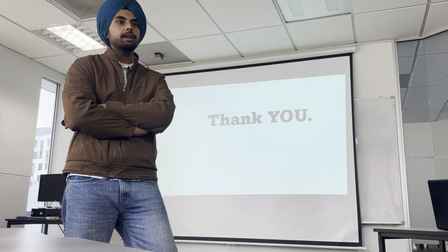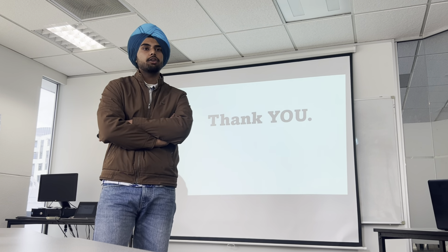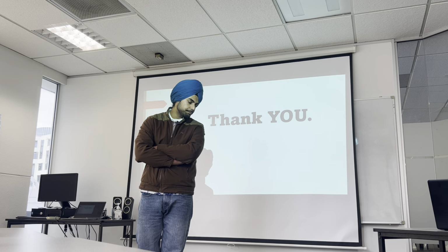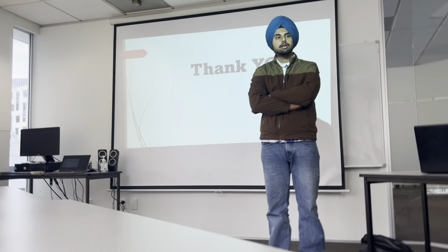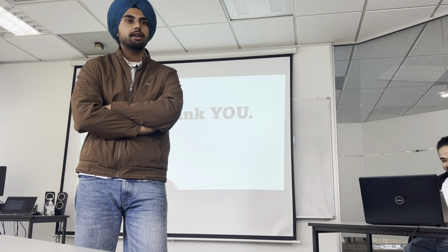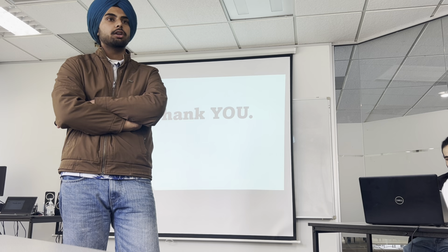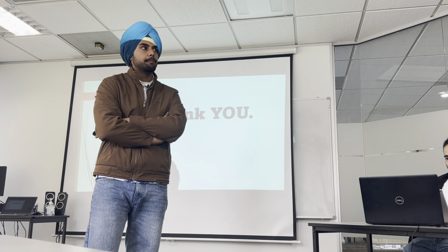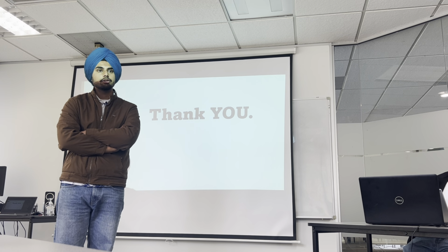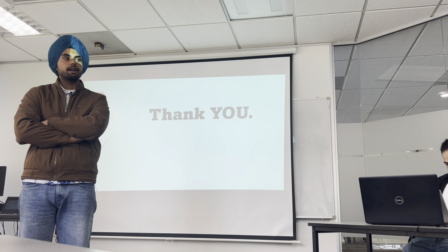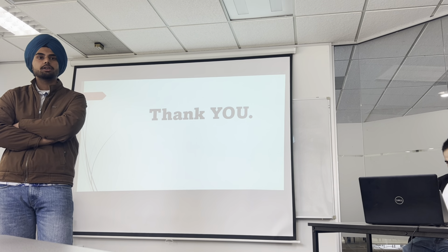It is very important because there are many advantages, because the project should have very few risks in it. We have to build client trust by making a bill of quantities, because the client also wants a bill of quantities for building his trust and putting accurate costs of each and